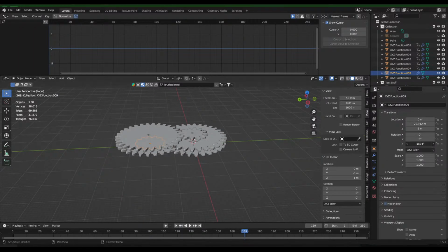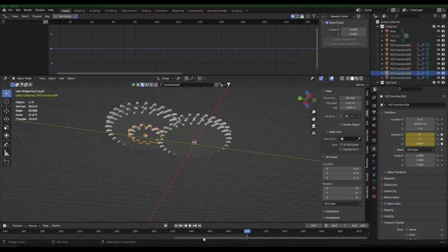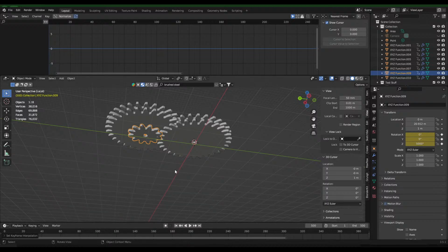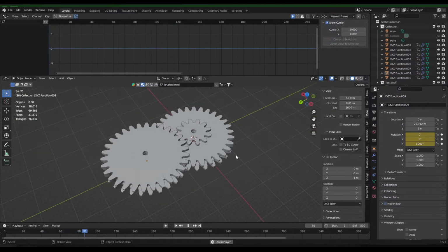So now let's just say change this back to 0. If I animate this, select I to keyframe, 500, why not? Oh, not 50, 500. If I go all the way over here to 500, just gonna set this at like 5,000 degrees of rotation. So it's going to spin around a whole bunch. Make sure both of those are selected. Interpolation, linear, so it's a constant speed. See if we spin around, those are going fast, and these are going slower.